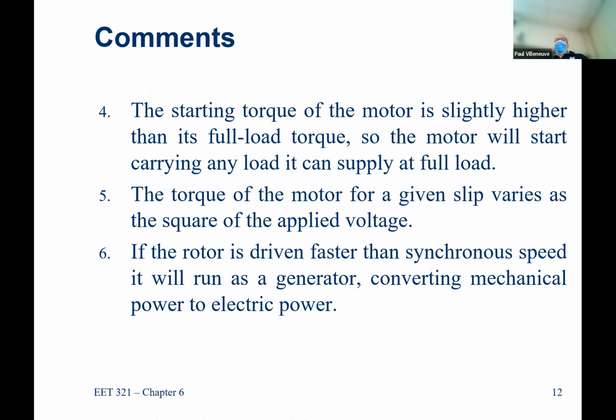You need to do that for wind turbines because, as we talked about in the other class, does the wind turbine always spin at a constant rate of speed? Better not, because there are times when it's running as a generator and other times it's running as a fan. Constant speed would mean that when the wind's good, it runs at that speed. But if the wind speed is too low and it's still spinning at the same speed, it's taking electricity in and spinning at synchronous speed, which, believe it or not, those wind turbines could in fact do.